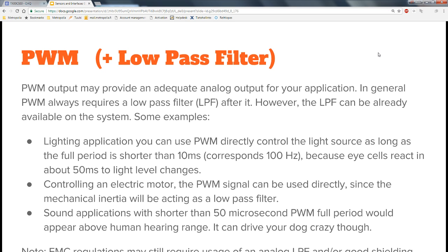Or there's also, of course, what I told you earlier about the pulse proportion modulation. It's almost the same, but a bit different. With pulse width modulation, you have a constant period, and you just change the width of the duty cycle. With pulse proportion, you can also change the off time. Basically you change off time and on time.